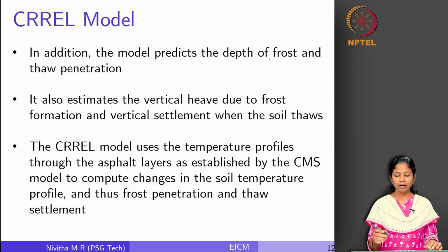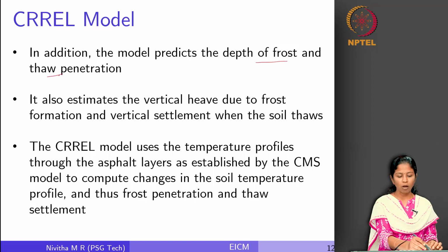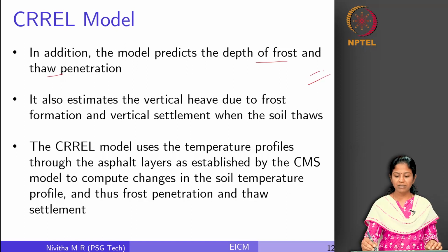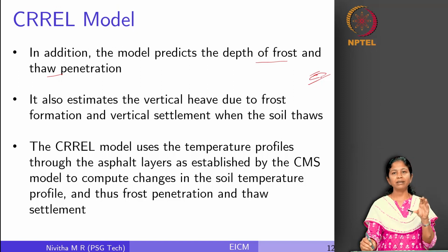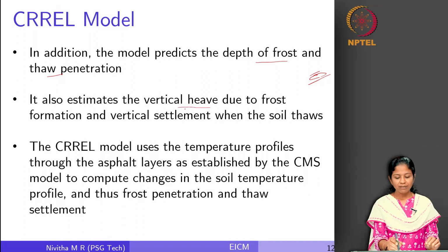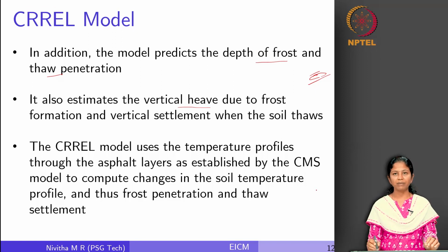Also, this model predicts depth of frost and thaw penetration, right. So, to what depth this freezing effect is observed in the pavement, and also when it thaws, what is the effect of moisture content and to what depth its influence is observed. And it also estimates the vertical heave because of frost and the settlement when the soil is thawing. So, this also we have seen.